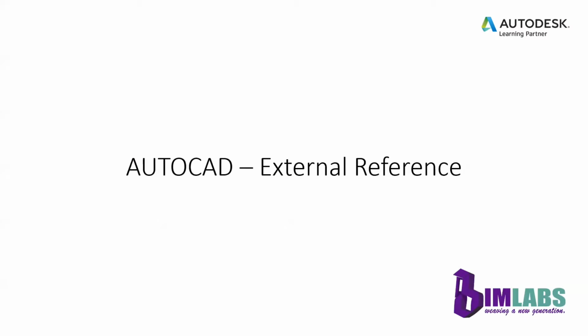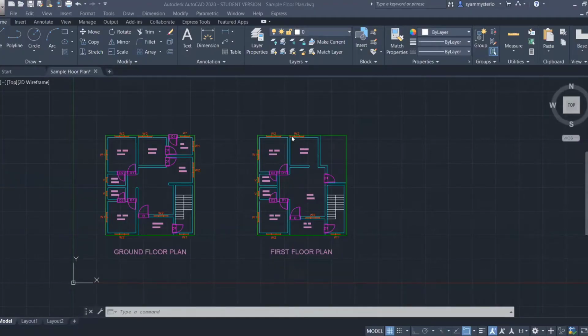So in simple words, the basic use of XREF is that we reference our current drawing with some other external drawing. For example, when we prepare a structural drawing, we may require to refer to the architecture plan to locate the positions of columns. In that case, we can import the architecture plan as XREF and locate the positions of columns with reference to the imported architecture plan. Okay, so now let's see how we can use the external references.